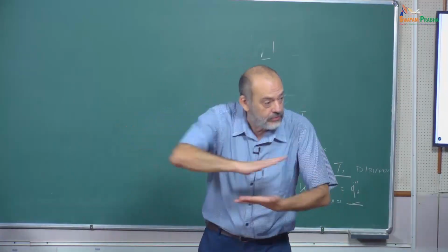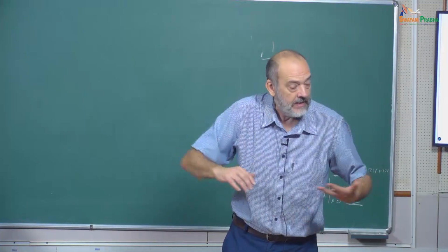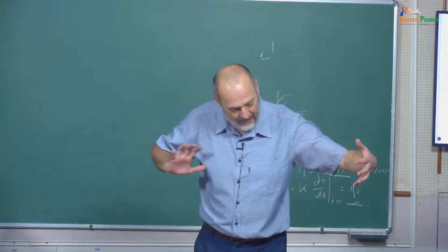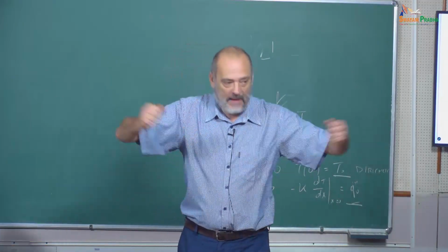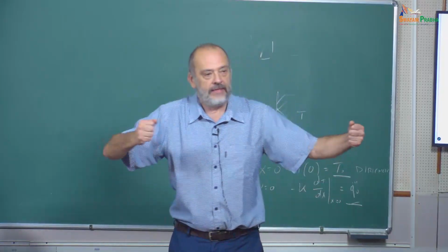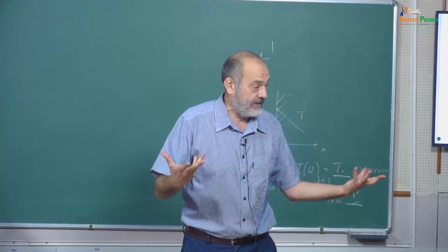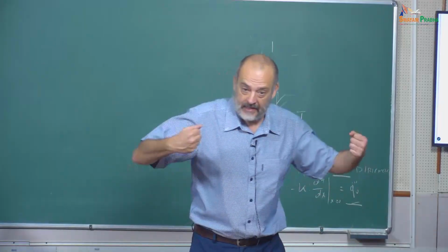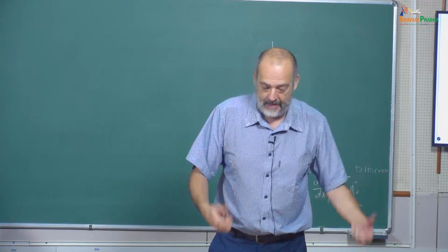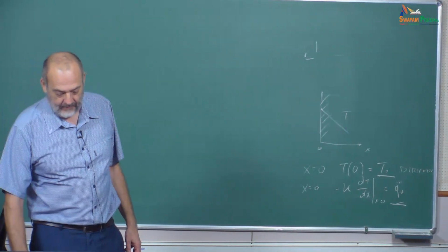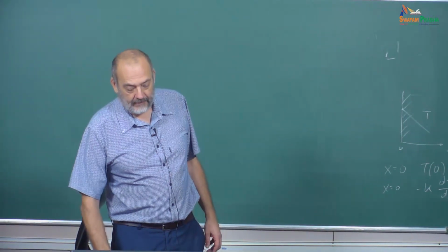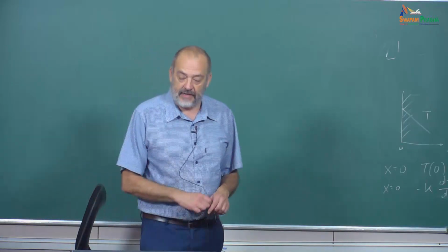So mu is due to the stresses in this direction. The other one is due to the fact that when we are trying to have an expansion or a compression, there is a force that is opposing this motion. Okay, so this is called dilatational viscosity. The dilatational viscosity is very interesting.